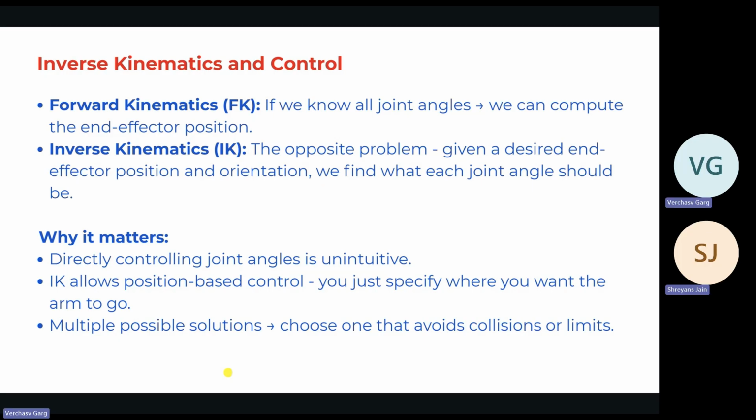I can divide these into c1, s1, c2, s2, basically theta 1 and theta 2. Right? If I give theta 1 and theta 2, then I can calculate X and Y. Yes? And this is forward kinematics. You just have to put the values in this equation. Now this just has 2 joints, right?